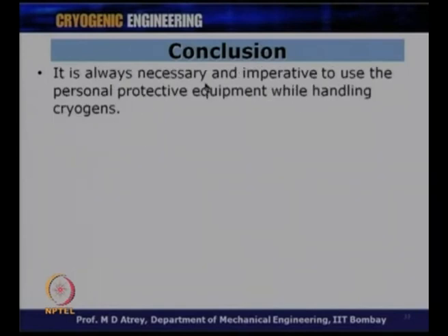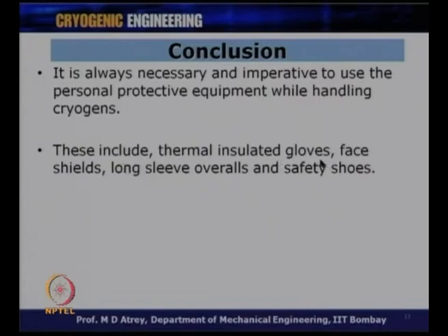It is always necessary and imperative to use personal protective equipment like goggles, gloves, overalls and boots, which are very important devices while handling cryogens. The entire body should be covered so that none of your body parts are exposed to the low temperature gas environment around you. These include thermally insulated gloves, face shields, long sleeves, overalls and safety shoes.